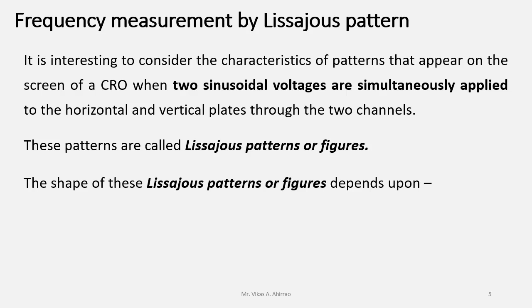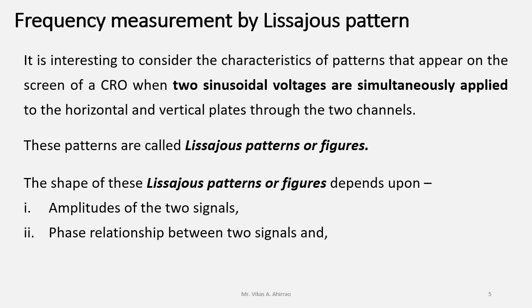The shape of the Lissajous patterns or figures depends upon, first, the amplitudes of the two signals, second, the phase relationship between the two signals, and third, the frequency ratio of the two waveforms. Some sample Lissajous patterns we may see here through different figures.